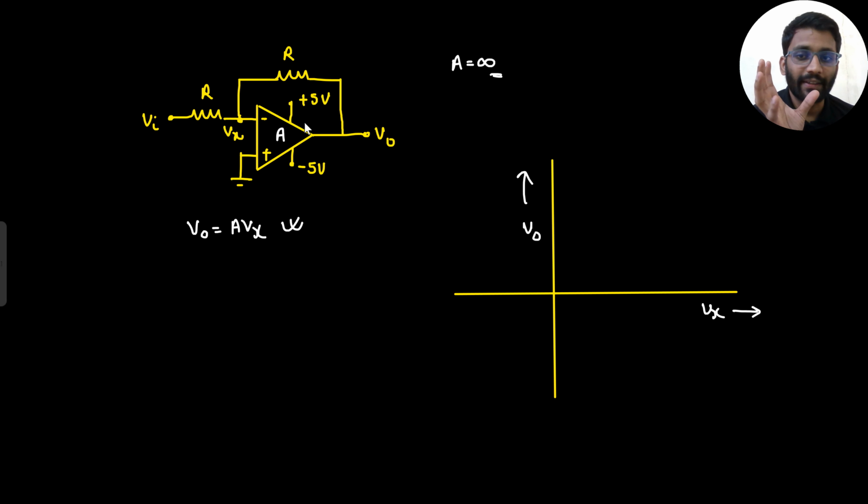Just look at the OpAmp as a comparator. What happens in a comparator? When the negative potential is higher, the output will be negatively saturated. So this will be the waveform, right? Forget about negative feedback or anything, I am just asking you to look at the OpAmp as a comparator only.